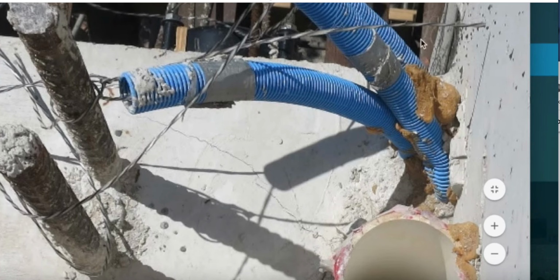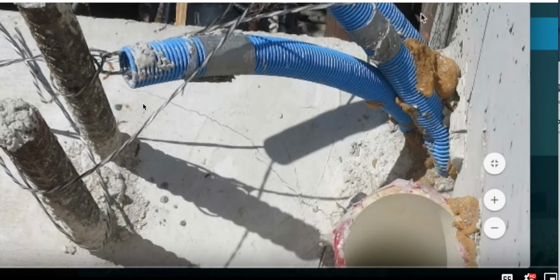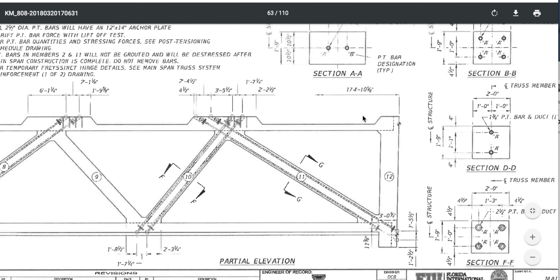They're all open cracks, because when you look at it, and I always said this was sagging, the bridge was sagging, and I only had one image, if you guys remembered. I did not have this one. I had the image of the chamfer saying, wait, this is indicating the deck is sagging. And then I kept arguing what came first, the deck or the canopy. You guys remember that? The deck or the canopy, and I called it the chicken or the egg. Which one came first as far as the cracking and all that? Now that we have all the evidence, all this evidence, rather, we don't have it all.